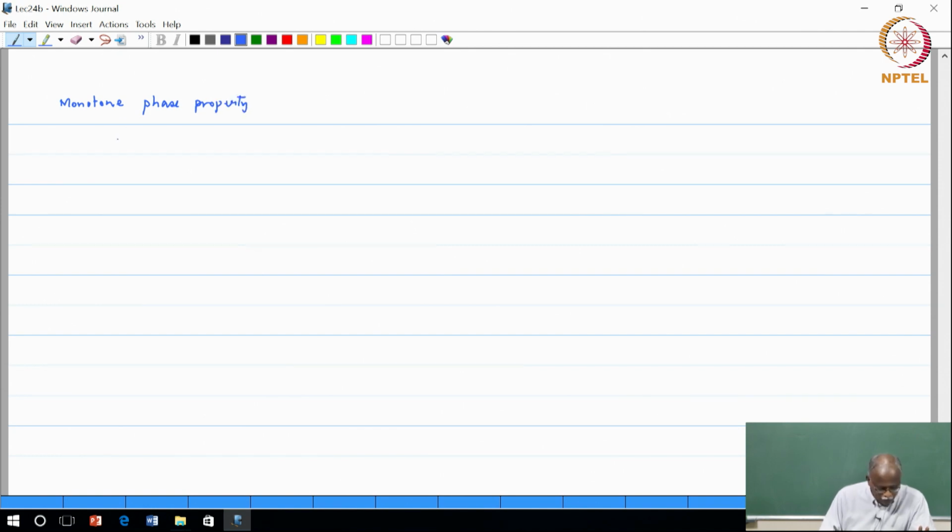Okay. So, if I have an all pass function h of z, given by (a conjugate plus z inverse) divided by (1 plus a z inverse), that is a first order stable all pass. Here mod a is less than 1, which is the location of the pole.